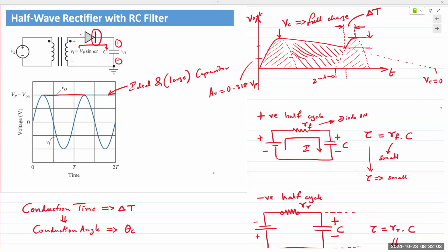Zener diode after this? We can use a Zener. A Zener would work the same as any regular diode in forward bias, but it will also conduct in the reverse bias. It's just not what we want. So, if it's a simple forward bias application and the reverse voltage is going to be less than the Zener voltage, then you could potentially use a Zener diode, because a Zener diode will work as a regular diode in forward bias. Depends. We can get Zener diodes made from like 2-3 volts going all the way to like hundreds of volts.